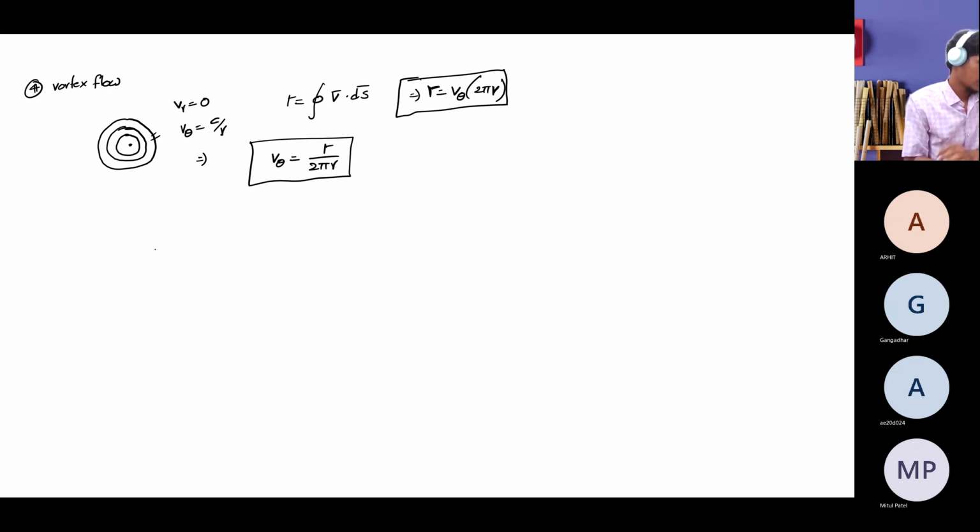Okay, next, the phi function, that is the potential function, the potential lines. Now the velocity vectors are like this in this vortex flow. Those are only tangential, in the theta direction of the circle. So your streamlines are also pure circles in this vortex flow. Then your potential lines are radial lines, because your radial lines and streamlines are perpendicular to each other.